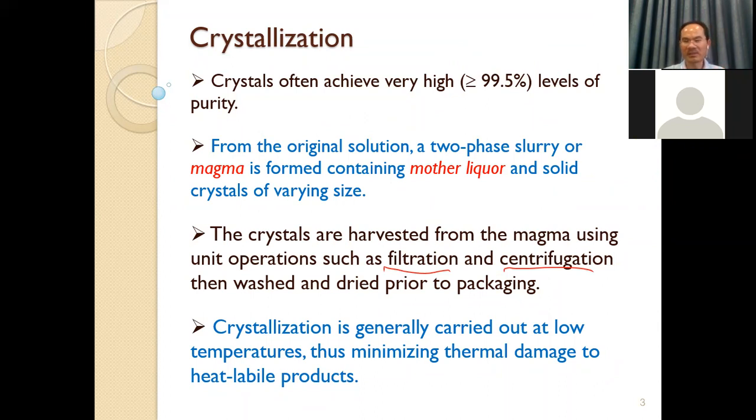And the advantage of crystallization is that we can operate at low temperature. At low temperature, you can minimize the thermal damage or thermal degradation of heat-sensitive products, because bioproducts are sensitive to heat. But with crystallization, you can operate at low temperature.